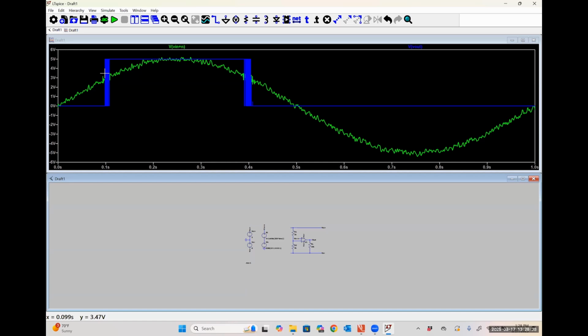So the first circuit that we're going to look at in Wednesday's class is actually going to use positive feedback and latching to get rid of these noise problems. If you ever buy an off-the-shelf comparator circuit, it will actually have some built-in latching, which is what we're going to be talking about in our next class meeting, so that you don't have to worry about this. Real practical comparators that you buy off the shelf take care of this noise problem for you. But if your noise is large enough, you would have to use the things that we're going to talk about on Wednesday in order to fix them.